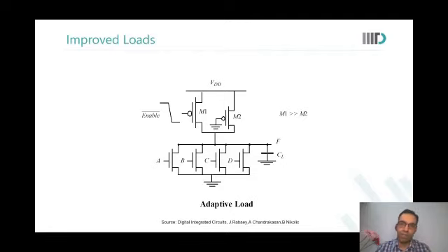But then you want to save area, so enable is to be generated irrespective of any input change. Okay. Clock comes, you generate enables because you know now evaluations have to happen. So we just need to save the rise delay in this case, and saving area also. Yeah. Not leakage. Leakage is not the focus here. No, leakage is saved because in the static case now only M2 is on.